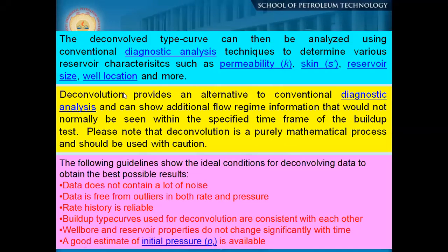our deconvolution process. Okay, so the deconvolution type curve can then be analyzed using conventional diagnostic analysis techniques to determine various reservoir characteristics such as the permeability, skin, reservoir size, well location, everything. Okay. So deconvolution provides an alternative to conventional diagnostic analysis and can show additional flow regime information that would not normally be seen in the specified time frame of the build-up test.